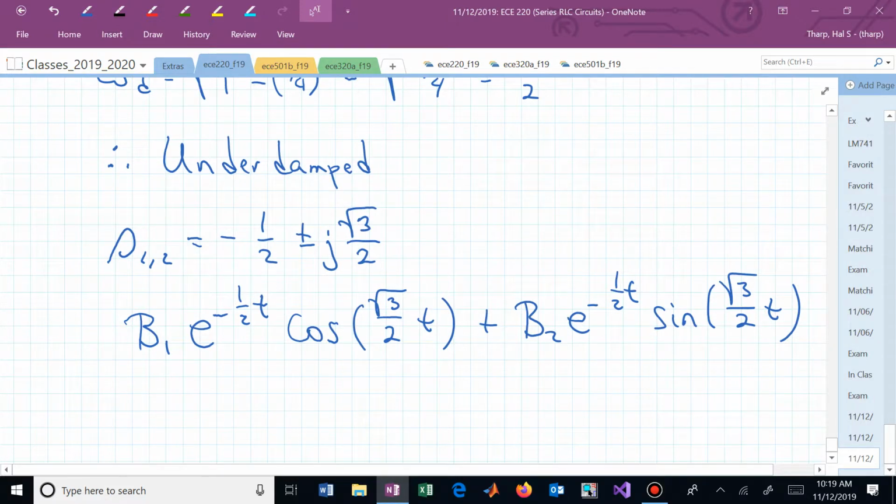How fast is this going to decay? When will this no longer be visible? How do I like to describe this? This is an exponentially damped sinusoidal response. We have something shaking. We know what it's shaking at. It has an exponential envelope within which it's shaking. When does that exponential envelope decay to nearly, or when do we say it's effectively reached its final value?